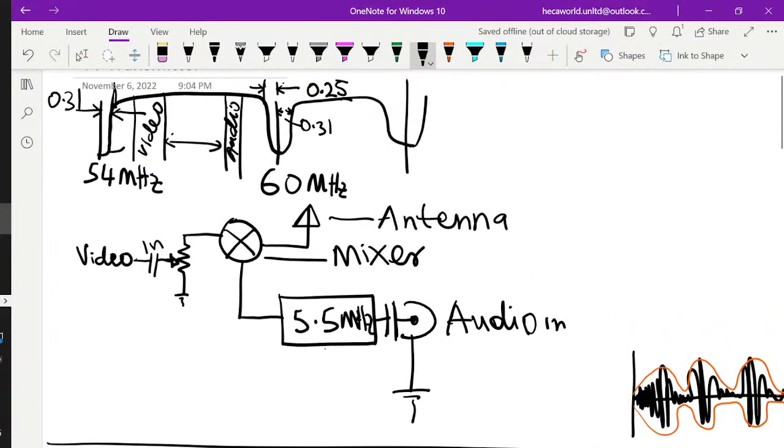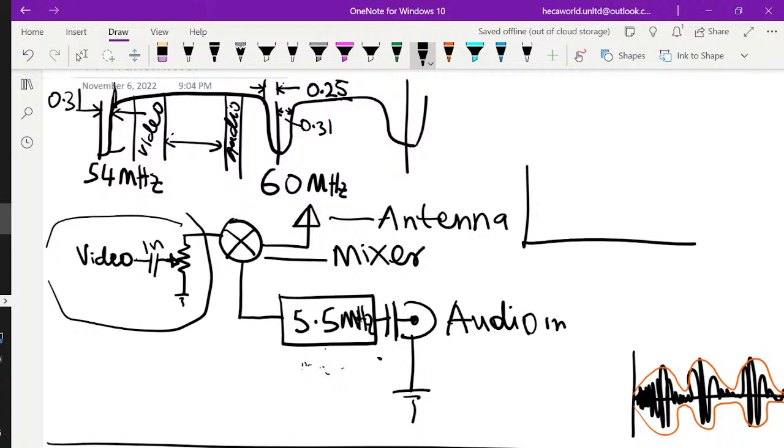But just look at this mixer that we've built here. We've shown here the block diagram. So there's a mixer here. You have an oscillator, not audio frequency, sorry, it's a 5.5 megahertz oscillator, and you're going to mix your audio signal, and then use that to increase the bandwidth of your video signal, and overall at your antenna level, you have a very big bandwidth.